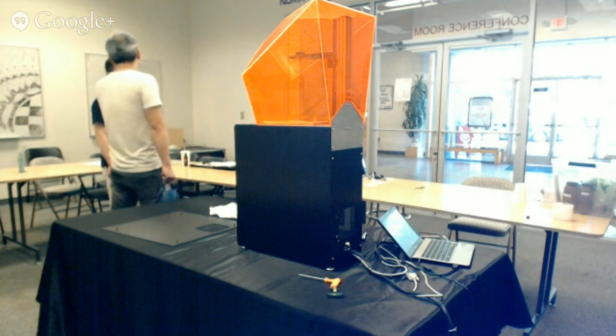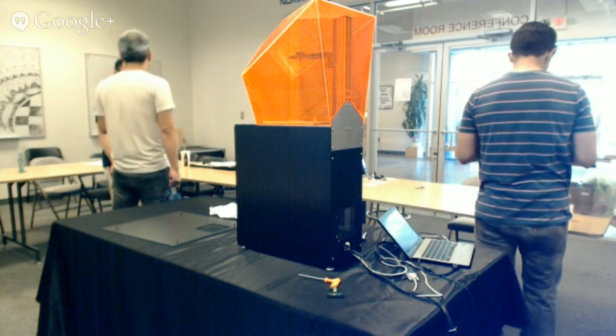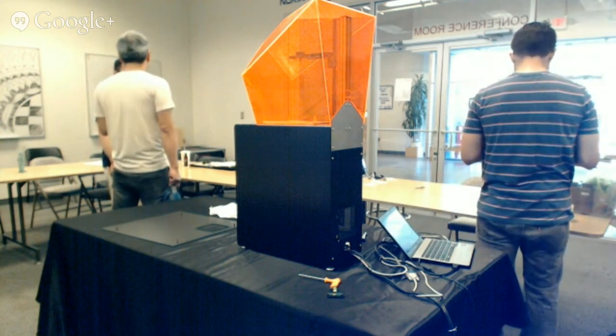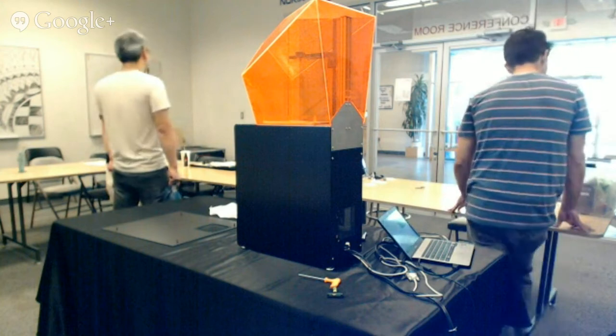I 3D printed and cast in polyurethane, and that worked out fine. That was how I tested whether the mold design would even be in the ballpark of being injection moldable. So I printed a version with a slightly different design, designed to be filled from the top with polyurethane, to validate that I could actually produce parts.